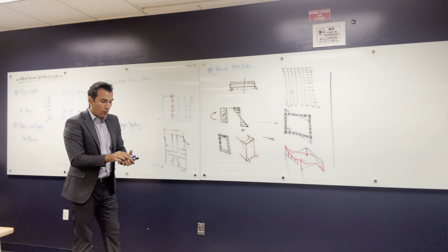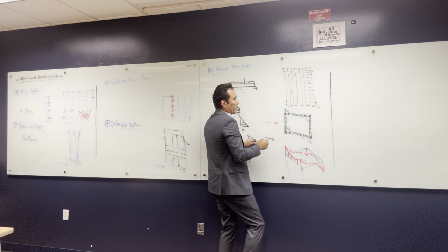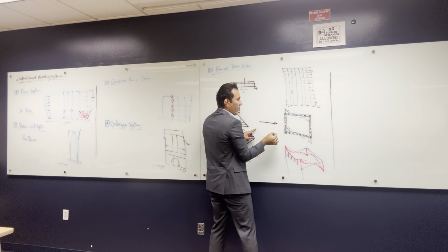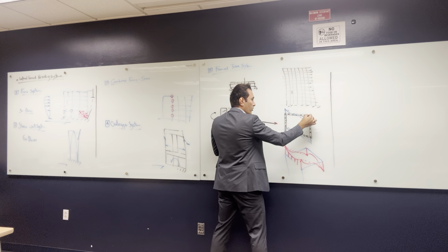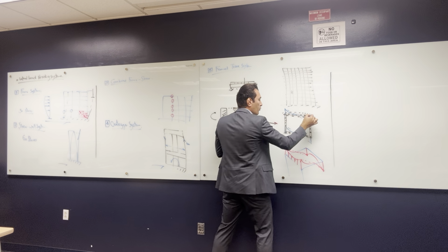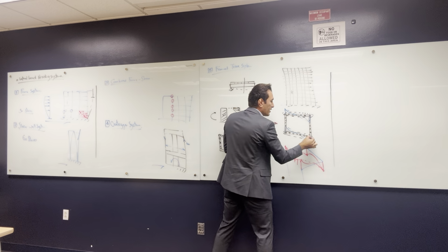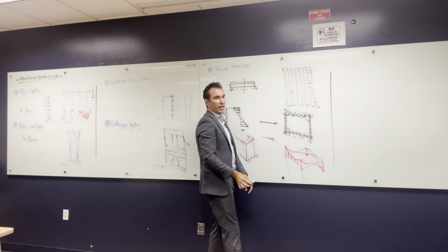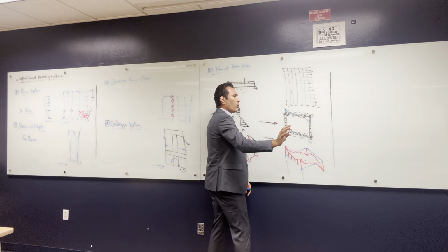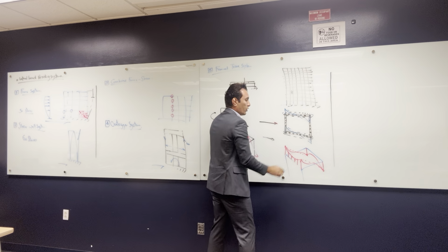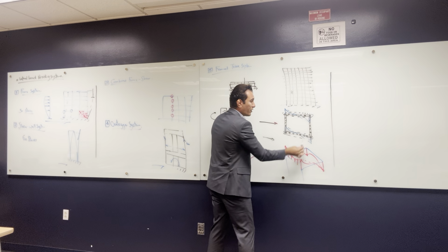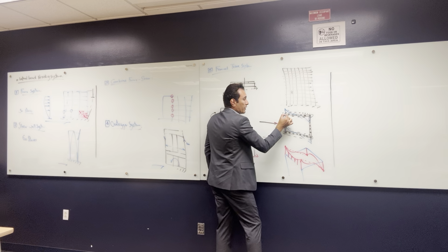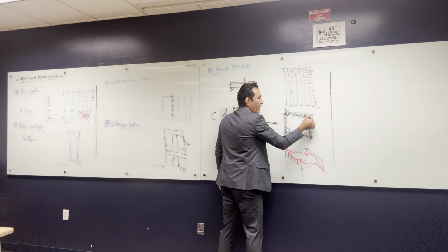And why is that so? Because when this gets an earthquake load that way, this perforated shear wall and this perforated shear wall are going to take most of the bending moment. But these are not getting anything, okay? They are getting a little bit, but not as much as these two shear walls. If the earthquake is coming in the y direction, these two are the ones that are going to be active. This one is going to have most of the stresses, and this one is going to have most of the stresses.